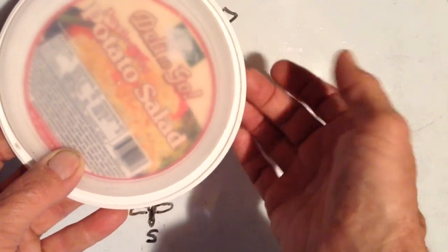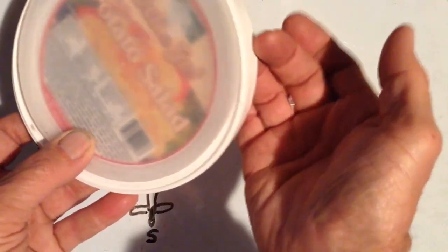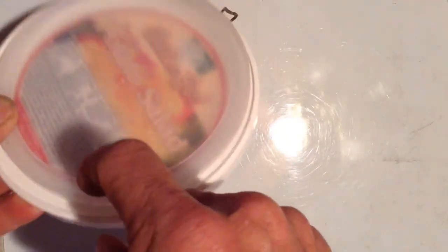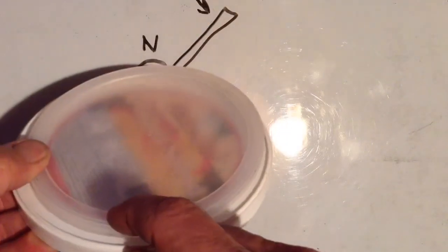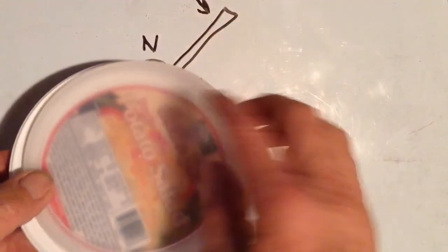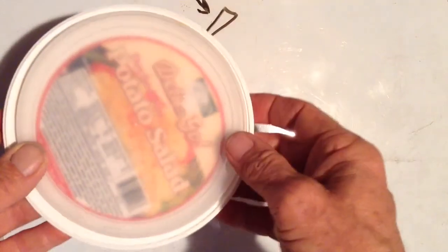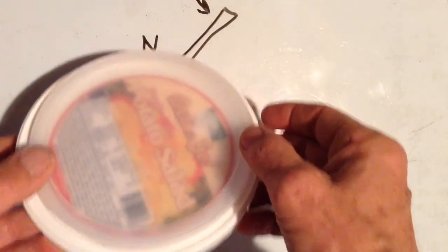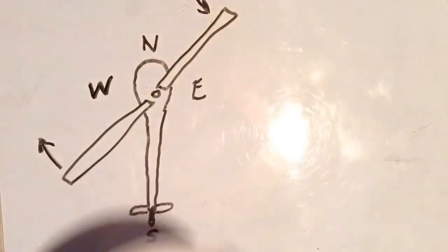With a gyroscope, pressing up to the east with the rotor spinning clockwise makes the rotor rise when it's facing south. So it leans forward and swings down low when it's in the north, so the plane of this rotor is tilted toward the north, which makes the helicopter go forward.